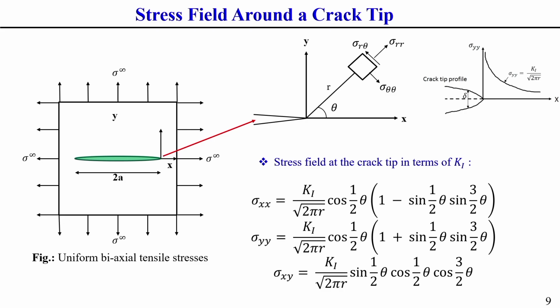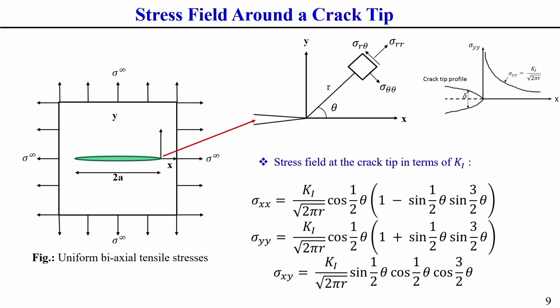Now we will discuss the stress field around a crack tip, how it looks. Based on this concept, we will discuss a very important parameter of fatigue analysis using what is called Paris law. This is a very important factor which is essential, and related things we generally derive from this stress field around a crack tip concept.